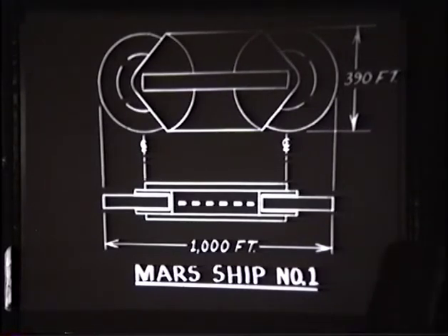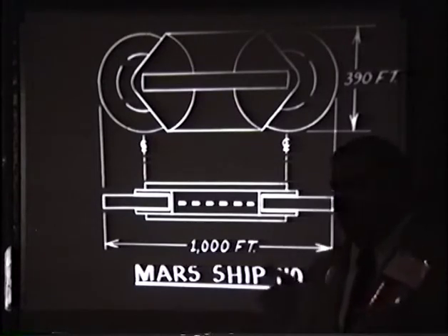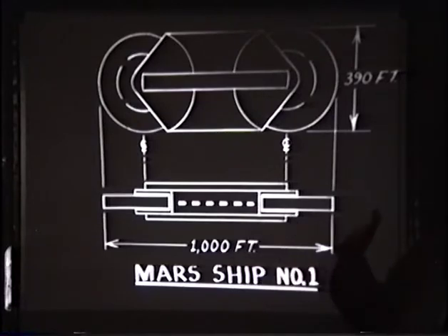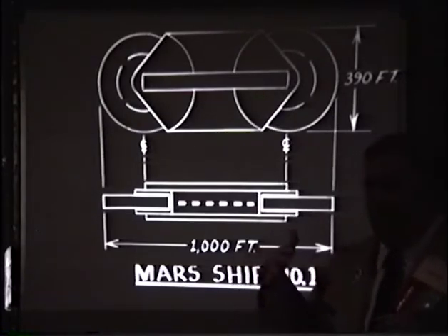Hard radiation. Hard EM radiation. It will fry your tail feathers at a distance. This is for use in space only. And at that, you don't crank it up near space stations or other spacecraft, especially if they're in the exhaust cone. And if you're going to use very high K factors, well over 10%, you've got to watch the neutron radiation. You'll have to have a shield between the engine and the payload at high K factors. At low K factors, you don't need it.